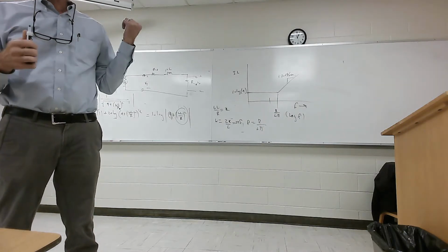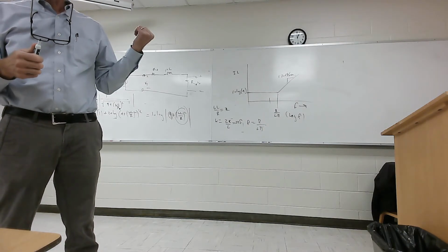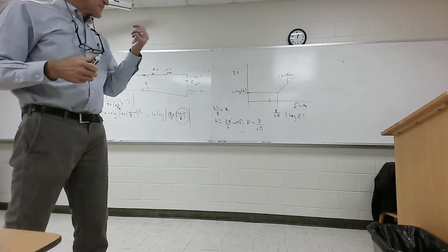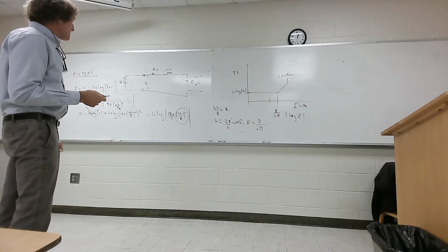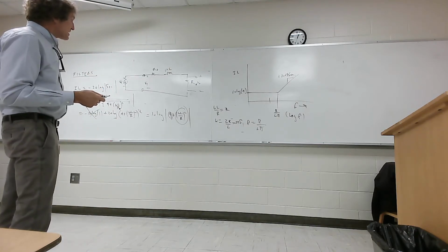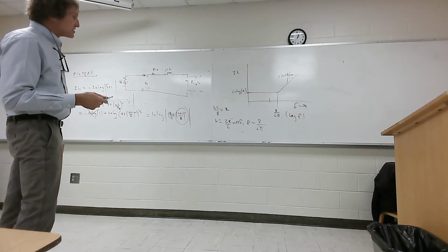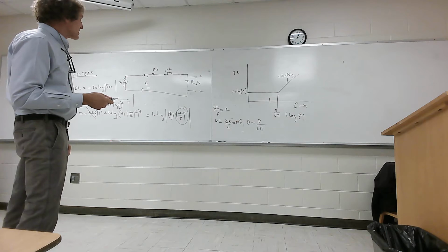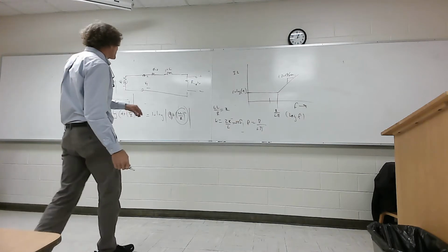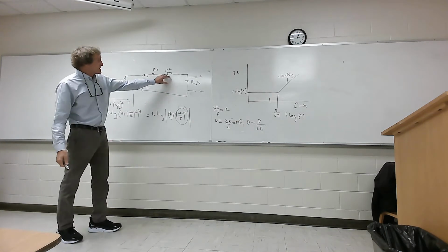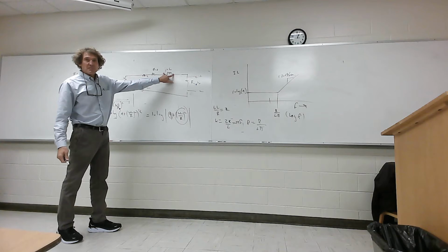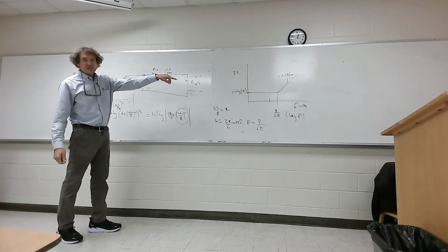Now, that happens to be a high pass filter. Do y'all follow me on that? Actually, this is the insertion loss. This is not a high pass filter, this is a low pass filter. If you just look at this, you can tell as the frequency goes up, more and more voltage drops there. It's a low pass filter, but that's the insertion loss.